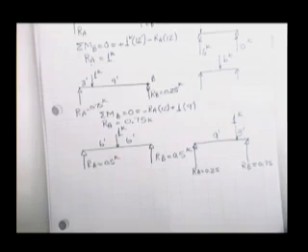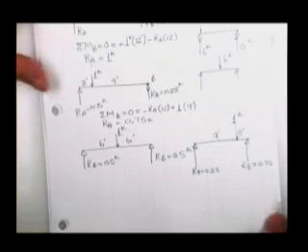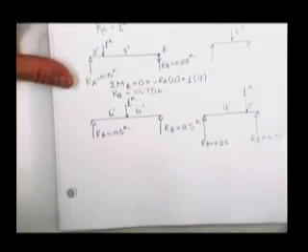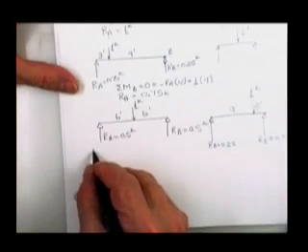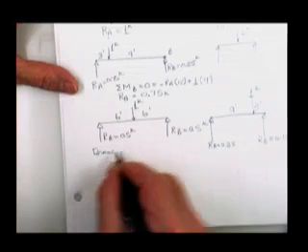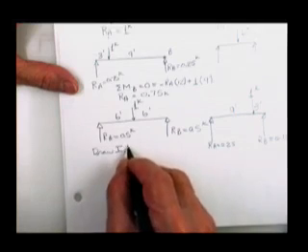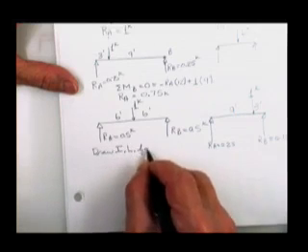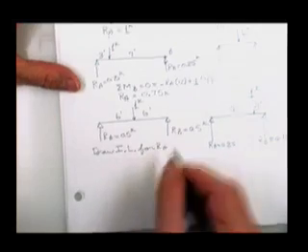Now, the problem with these diagrams is they look a lot like shear diagrams or moment diagrams. And so people start getting the idea that what you've really got is a shear diagram or a moment diagram. And that's not the case. But it is a subtle difference. An influence line. Draw an influence line for the reaction at A.